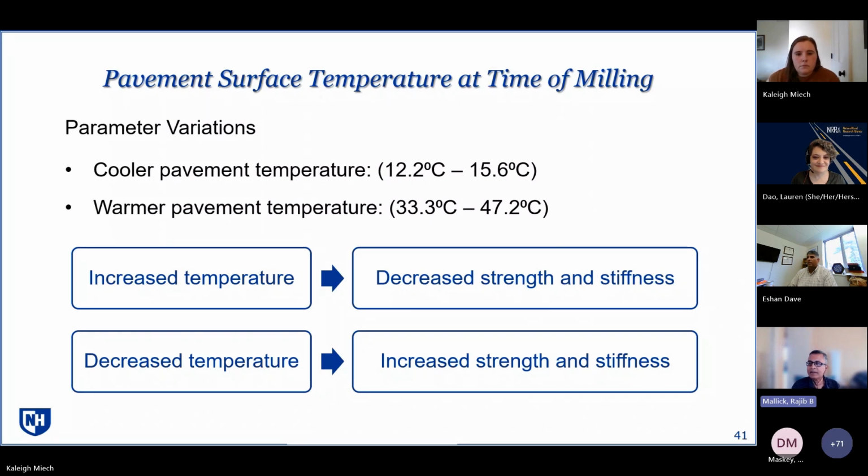I think that was a good summary of the project. And Deepak, I think that was a relevant question. I just wanted to say a few things about this project. One thing is that theoretically, if you look at the problem, you are exerting a very high amount of stress on the pavement. And you can expect stresses going below the milling line that exceed the tensile strength of the mixtures. Theoretically, that is expected. Now, what we see in the field is a mixture of results. Sometimes we see the effect, sometimes we don't. And I'm not counting the results which show abnormally high resilient modulus after testing. Those do not count, actually.